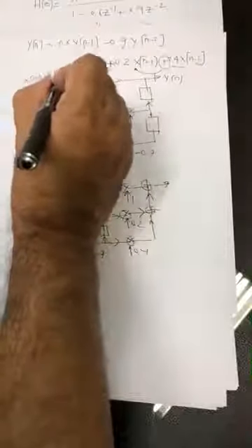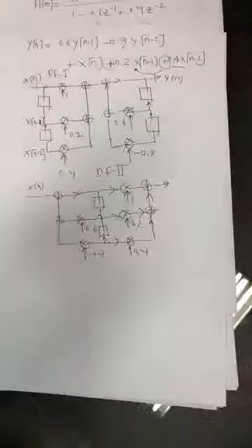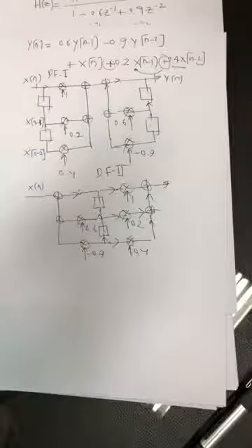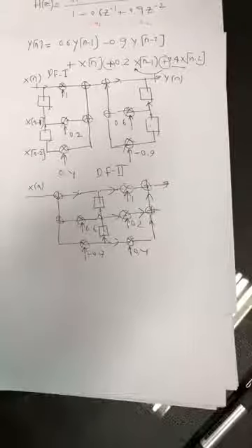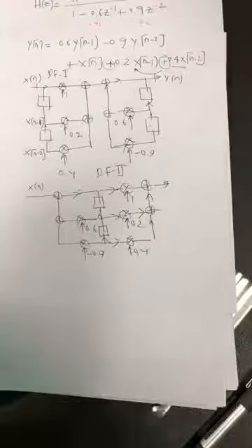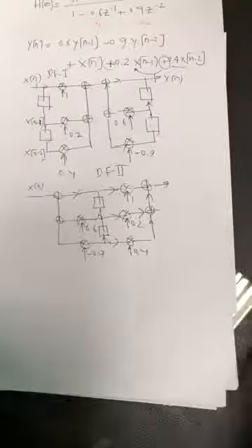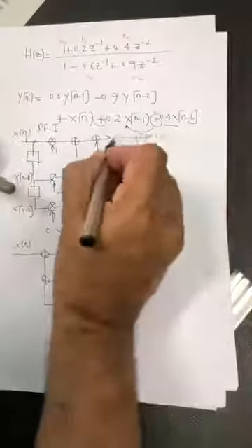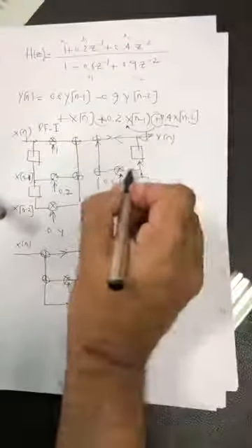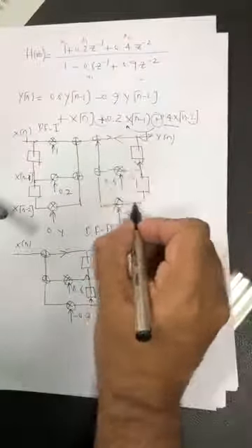This is direct form 1. And then is the transpose. Transpose direct forms are where you only need to change the direction of these arrows. So let's change their direction using a red pen. Change the direction of the arrows.